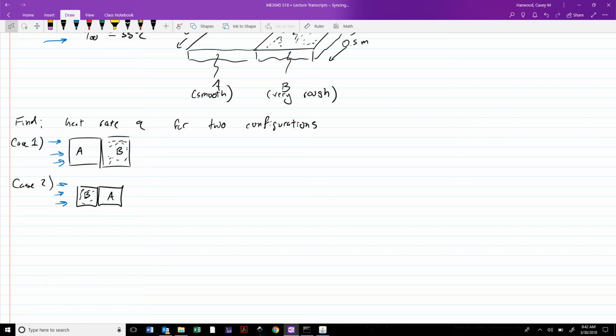So just on observation, and the assumptions that we're going to use to solve this, the idea here is that by a roughened plate with B, this means that if the flow is not yet turbulent when it hits that plate, that roughness is going to create turbulence. It's going to be like wind over a mountain range. It's going to generate those eddies in the swirling flow and prevent any laminar boundary layer from developing. It just goes straight to turbulence.